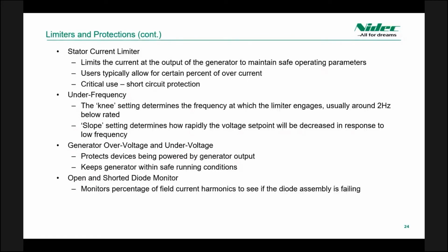The user may also want to monitor the diode assembly that is in charge of rectifying the exciter output. The open and shorted diode monitor observes the harmonics in the field current, and the user sets a percentage threshold for when to activate the fault.